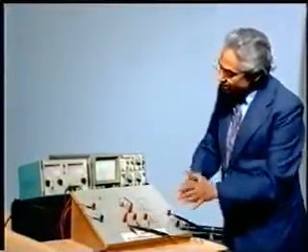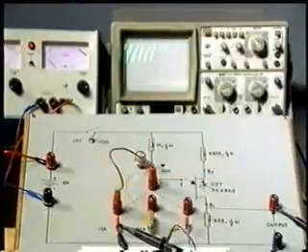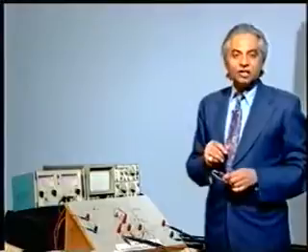If I make that constant and change this, this pattern is changing, as well as if I make this potentiometer as a constant resistor and change the value of the capacitor, then also it is changing. So friends, what we have verified here? We have verified that with the help of either variable resistor or variable capacitor, we can change the relaxation time, and hence the pulses will be obtained either earlier or later. So the firing of SCR or TRIAC, whatever it is where this pulse is being given, that will change, so the firing angle will change.